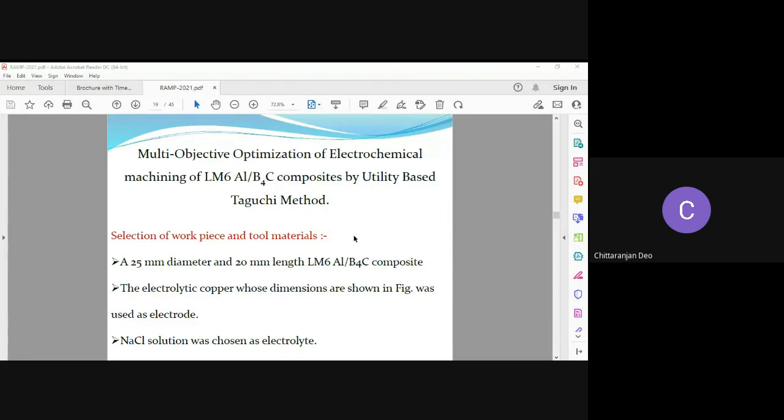We choose this aluminum LM6 base material because it has excellent resistance to corrosion in atmospheric condition and excellent castability, but it has medium strength and cannot be heat treated. Its strength reduces rapidly at high temperature. Due to its poor elasticity, it is difficult to machine.